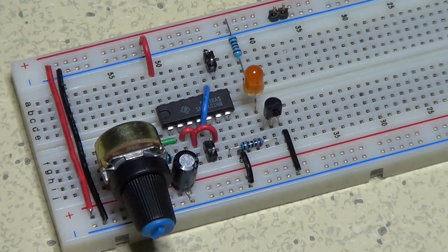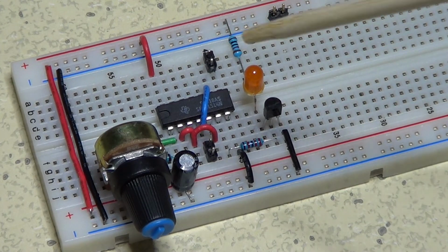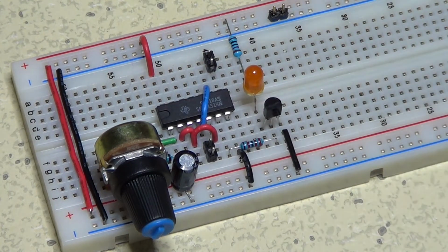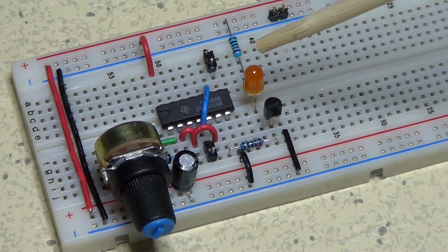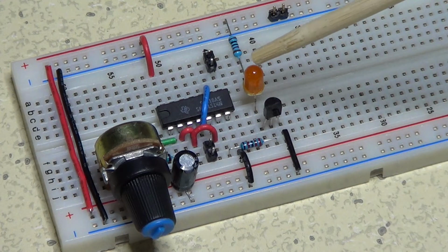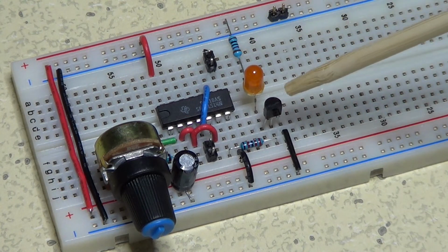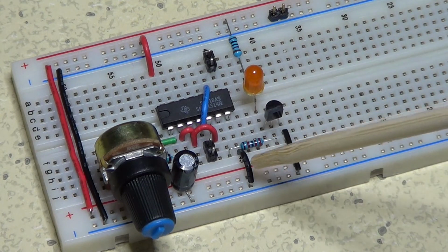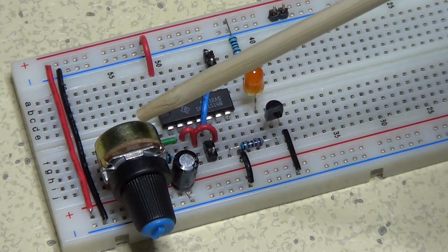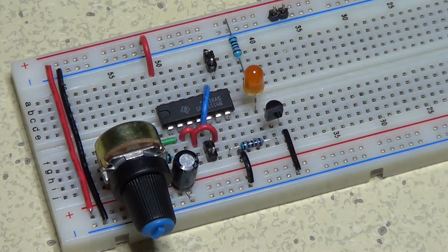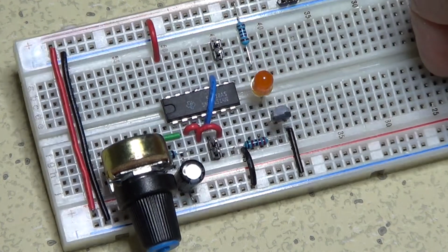Here is the generator mounted on the breadboard. This is the SN74LS14, which is powered through pins 14 and 7. This is the LED, which is orange instead of red, but since they have approximately the same forward voltage, it works just fine for our scope. The LED is powered through this transistor, and here is the 2K potentiometer to modify the frequency of the oscillation. The potentiometer is of course in series with a 100 ohm resistor, which is visible here in the back.